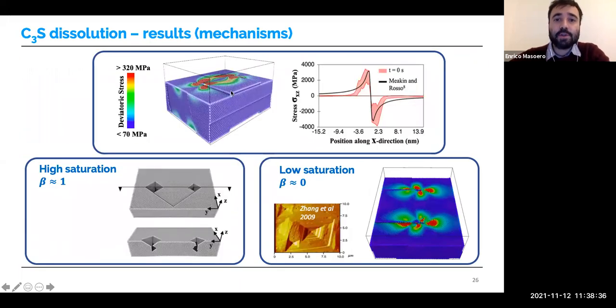And then we generated a screw dislocation. So we lifted some particles, we created the ramp, and this is how you create the 3D morphology of a screw dislocation. What is interesting here is that when we deform our structure, we do get a local stress because we are stretching the particles, but this local stress is predicted by the model. They are not imposed like you can see in other kinetic Monte Carlo methods, because the particles are off lattice, so they can go everywhere. You can relax the strain energy, and this develops the corresponding stress. The stress that we are predicting from this distortion is consistent with what the literature indicates to be the stress profile near a screw dislocation.